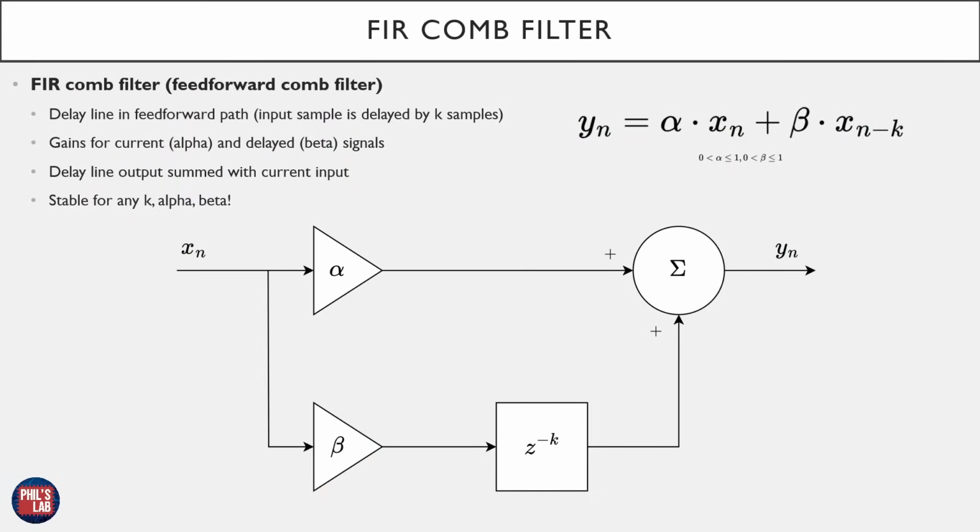Now we've seen the basics of delay lines and how simple they are to implement, we can move over to comb filters. And we'll see why they're called comb filters in just a bit. Again, comb filters come in various flavors. They can be feed forward or FIR filters, as well as feedback, so IIR filters. In this video, we'll just be looking at FIR filters to start with.